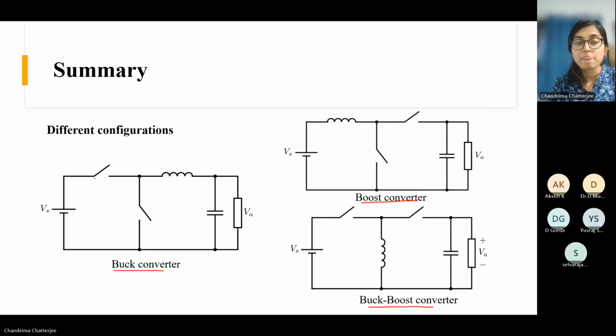So here, each contains one half bridge. Okay. So basically, the buck converter you can also draw like this. In that case, you will see it contains a half bridge. So the configuration is something like this. This is just to show you that you can generalize these circuits. They are basically different combinations of inductors and switches. You just rearrange the inductors and switches, and you will get a new converter.